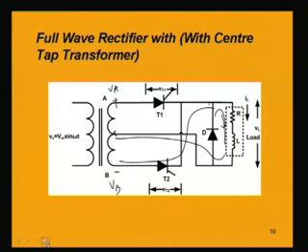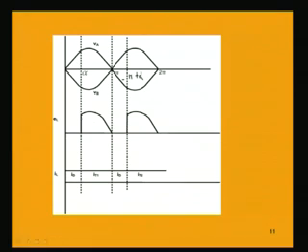So, it will be continuing, and what is important here is that it is a full wave rectifier, that means we are not getting a negative voltage across the load as we are getting without the flywheel diode.